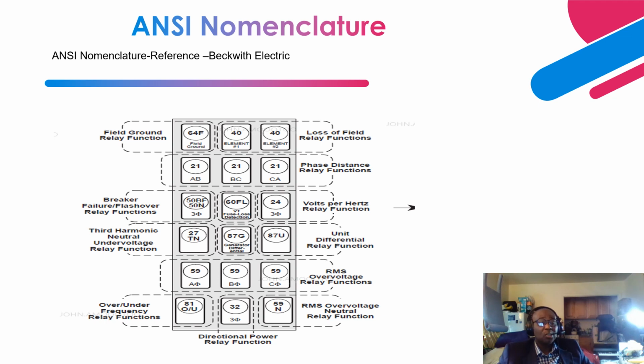As you can see over here, this is also based on impedance. It's an impedance-based relay, so it utilizes CTs and VTs, voltage elements, to calculate the impedance. And it is also made in such a way that it is more directional. Basically, it's pointing towards the generator as well.